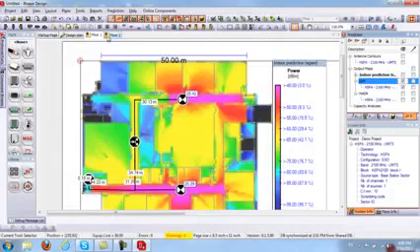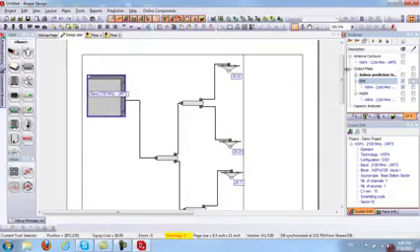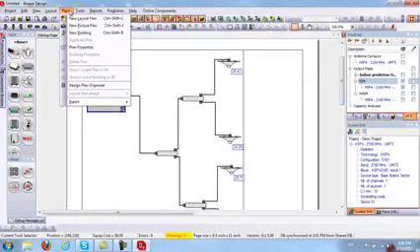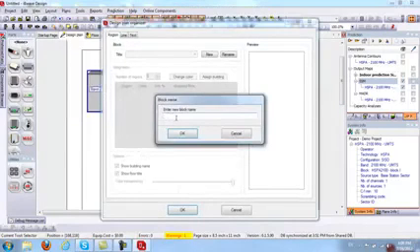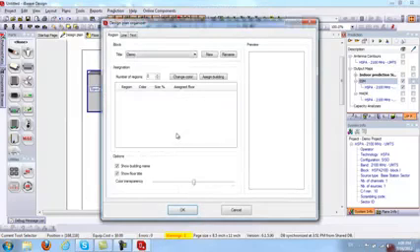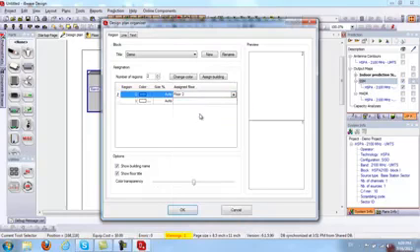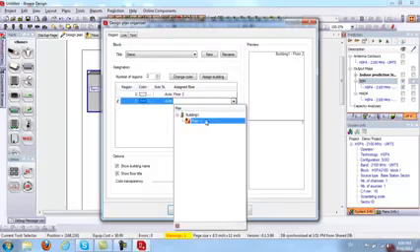So next, what I want to do, if we go back to the design plan, so here we have the option to organize the design plan tab, and to do that you actually go to plans and select design plan organizer. So I'm going to give it a name. Once you click OK, you have to add the number of regions depending on how many floors you have. So in my case, I have 2 floors. I'm going to select 2 regions. I'm going to associate a floor to each region. So we have floor 2 on top, floor 1 on the bottom.